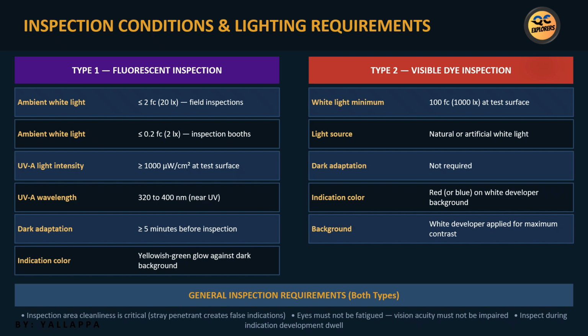Now, from practical field experience, poor lighting control is one of the biggest reasons for missed indications. Even a high-quality penetrant system becomes unreliable if lighting conditions are incorrect. So lighting verification must always be performed before inspection.